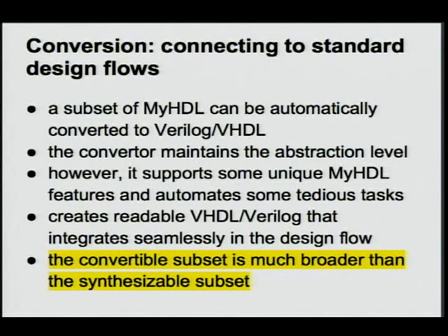And actually, I know just recently someone who was learning Verilog told me that he found it easier to write MyHDL first and then look at the Verilog output to learn how Verilog works, which is true, I think, but also a nice compliment. The important thing here is that conversion is not restricting you for implementation, because what you can convert is much broader than that synthesizable subset that I told you about. You can do much more than just the RTL level, okay?